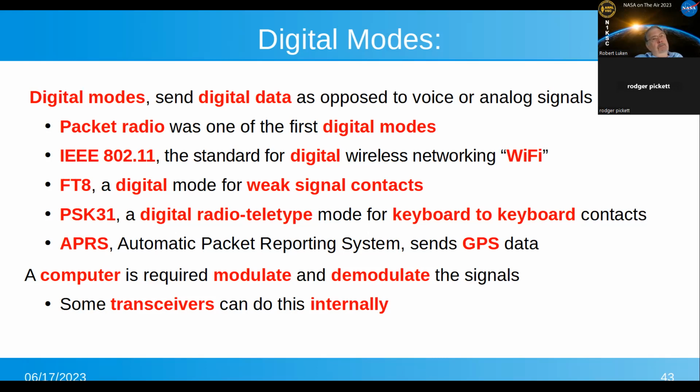You maybe get a 20 dB antenna, so now you're up to 80. And I guess you get to count the antenna on reception, so another 20. So you've got 100. You still have 150 dB down with all of that. He said, you get on there with voice. Hello, moon. Hello, moon.